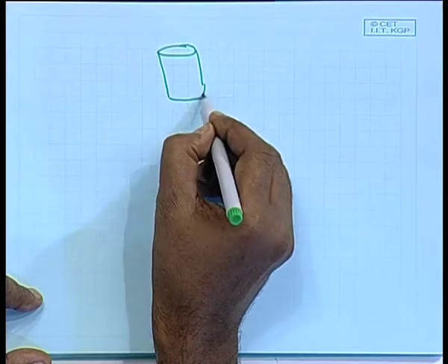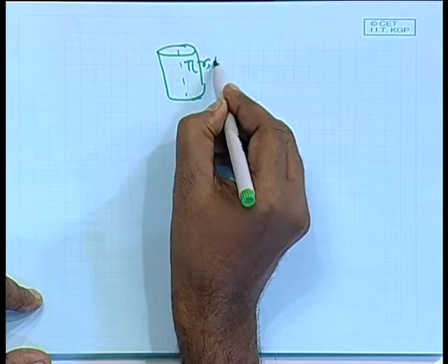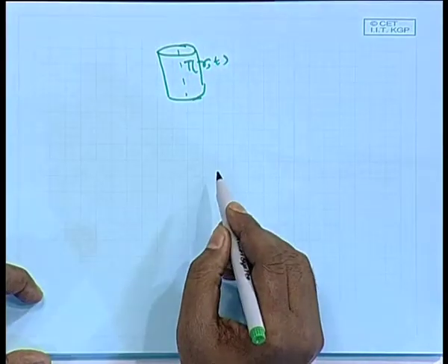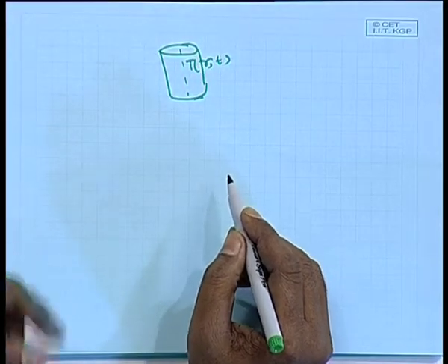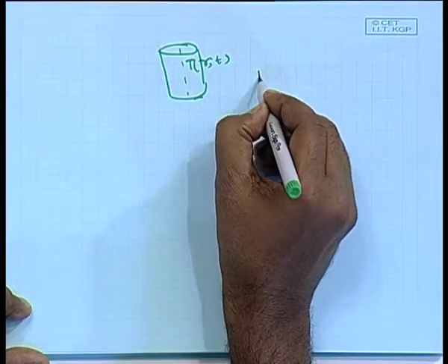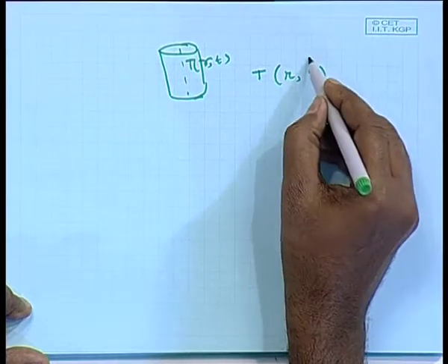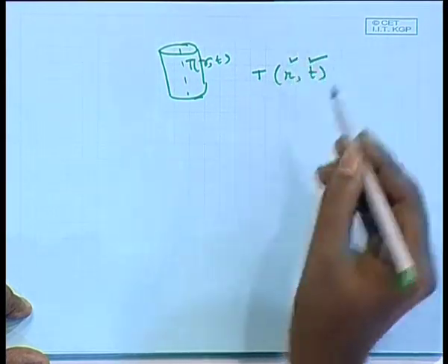Like the example I was giving, you are having a nuclear fuel element, whose temperature is a function of r and t, and the z dimension is so long that all the variations of temperature in the z direction are negligibly small. So, in this case the governing equation will be a function of r and time. So, it is a function of time and a function of space.